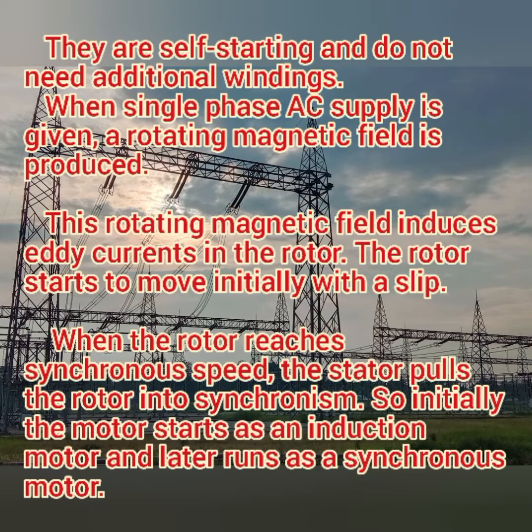When the rotor reaches the synchronous speed, the stator pulls the rotor into synchronism, and so the motor will start initially as an induction motor, and later it reaches the synchronous speed and runs as a synchronous motor. In this way, the hysteresis motor works.